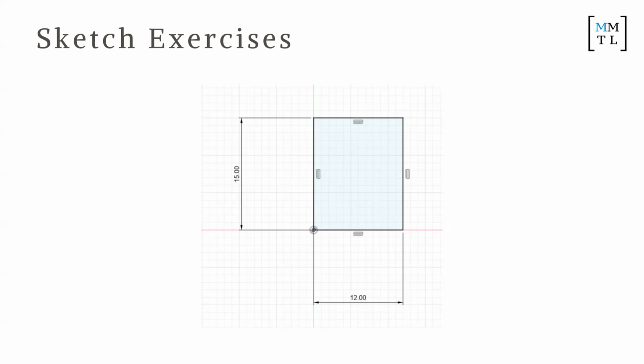Basically you can give it a value, so hover over it. This is just for yourself. Rectangle, 15 by 12. Now that line is always going to be a fixed value. The reason why it's still not black is because it's connected to something else.